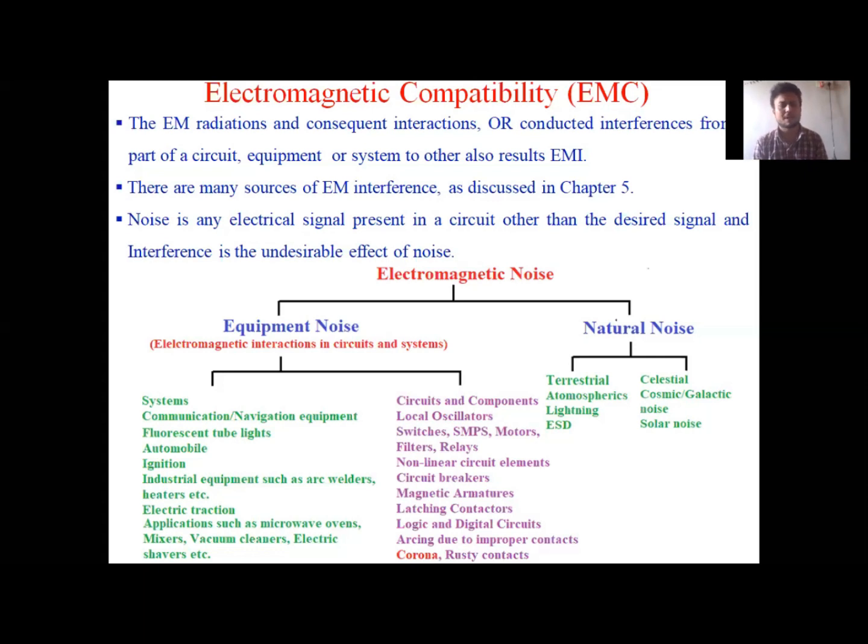Different equipment offers different levels of electromagnetic interference, depending on the type of component that you are using in your equipment. So what are the various components that you will be using in any electronic device? Cables are there, right? A simple cable acts as a transmission line. If the cable length is comparable to the wavelength, the cable itself acts as an antenna.